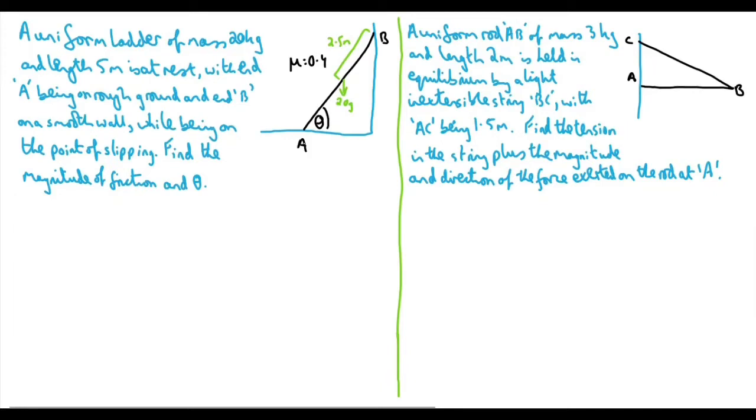Now then, if it's resting on the ground here, there's going to be a reaction force upwards from the ground at A, but also, just to differentiate things here, you're going to have a reaction against the wall at B here, otherwise the ladder would be just pushing straight through the wall and falling through it.